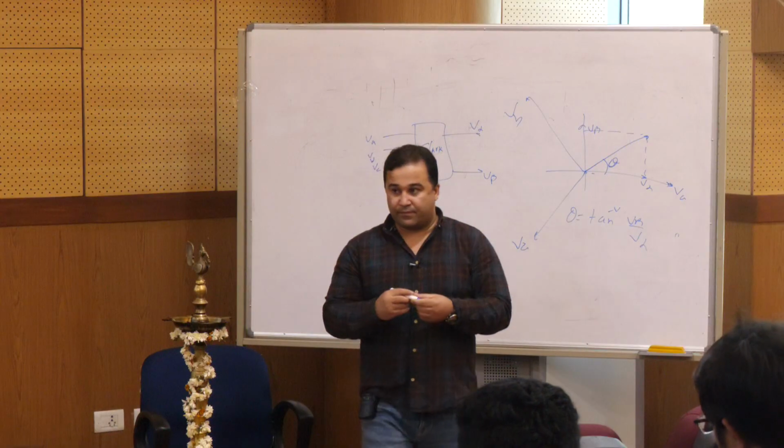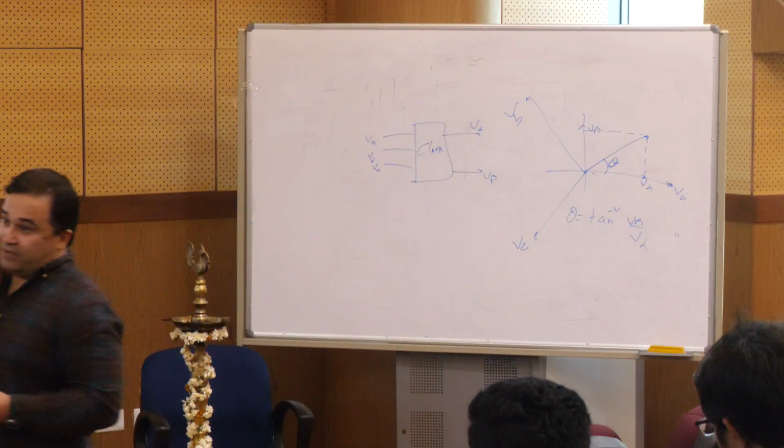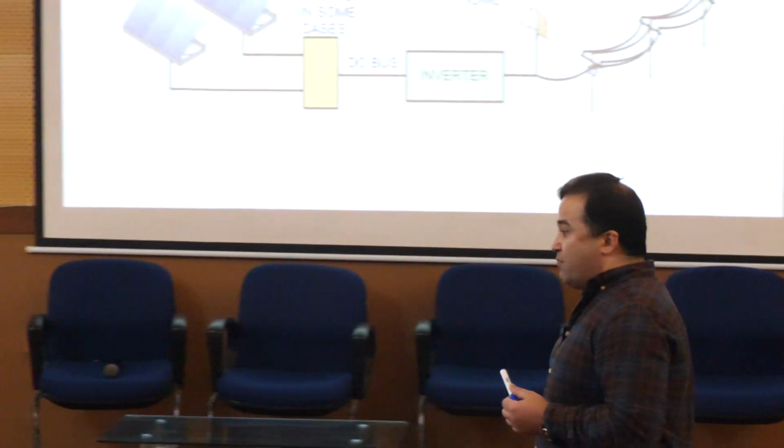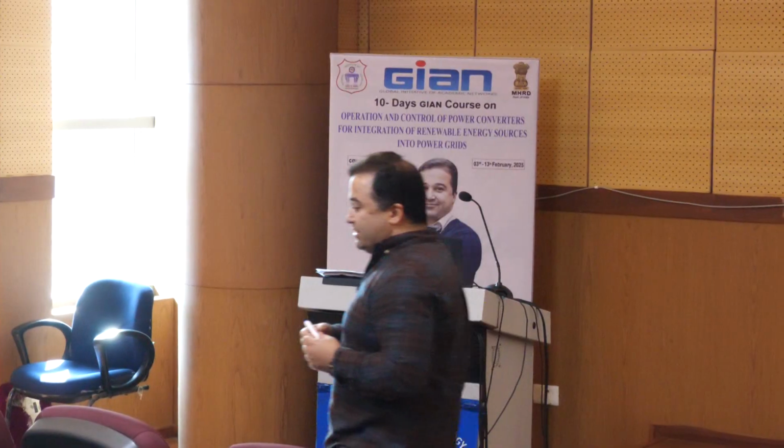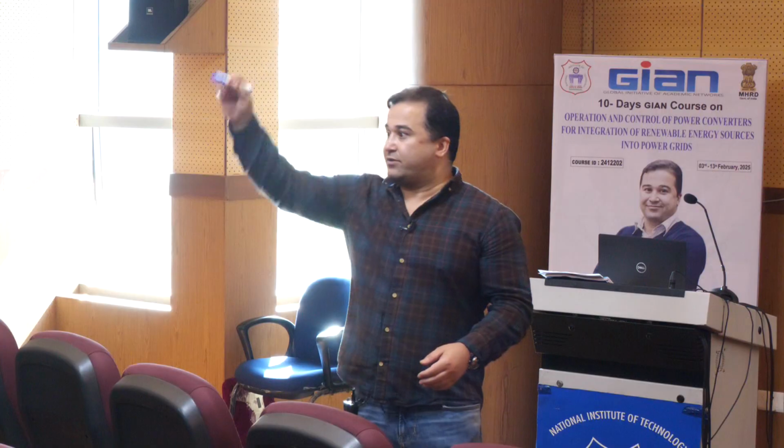It requires minimum voltage level. Minimum voltage level, or threshold. If it requires a threshold, how can we set this threshold? Yeah, actually, the question is a little bit tricky because if you have the minimum voltage, it means that you don't have a stable voltage. So when you don't have a stable voltage, then PLL cannot be a useful method for that one because instead of providing the angle like this one, it provides like this one.